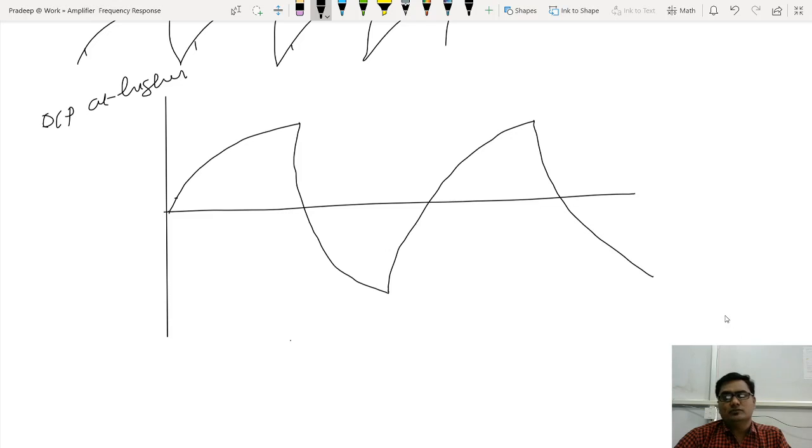That's quite okay. So this is my output voltage on the x and y axis. Now look at this. This is the 0th level. I'm talking about the amplitude, the output voltage magnitude. This is a 10% level, here it is a 50% level, 50% of maximum output voltage, and somewhere here it is the 100% level. I'll say maximum is 100%, and then here somewhere it is the 90% level. So this is 90%. This is simply output voltage versus time.